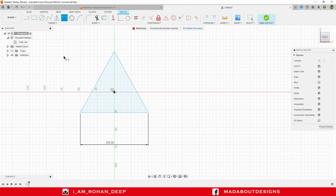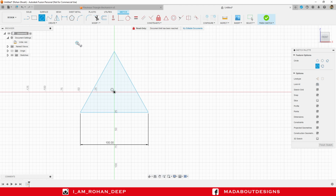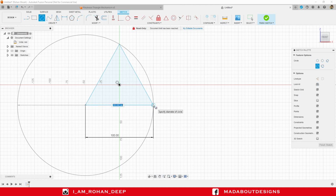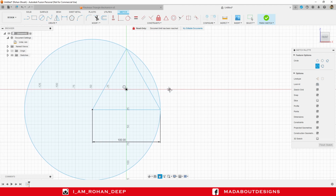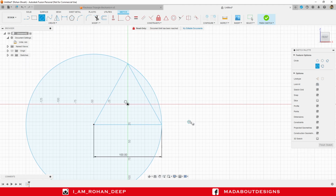Now go to Center Diameter Circle. Select the center as this vertex of the triangle and give it a diameter of 200 mm. So the other two vertices of the triangle will be on this circle. Repeat the same step twice for the remaining two vertices.